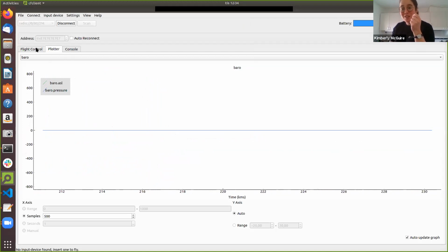But you can use the barometer in the state estimator. So that's maybe something for you guys to try out, because if you would use the barometer and you would change your position, no matter what there is underneath, the pressure will stay the same. It's just a lot noisier than the height measurement. So that's just something to be worried about. But there are all kinds of things that you can try out and play with.